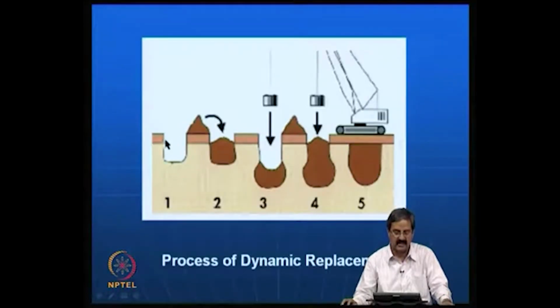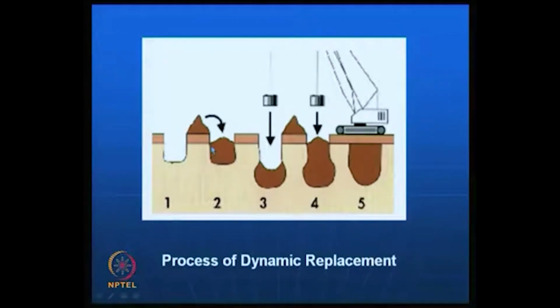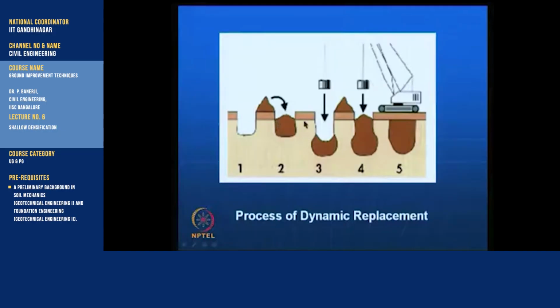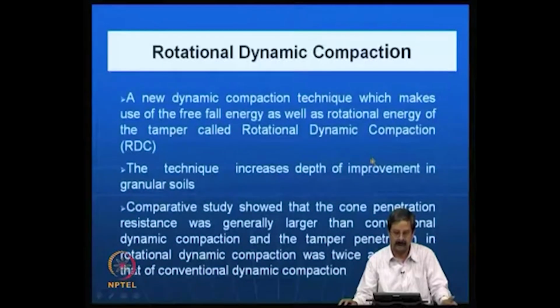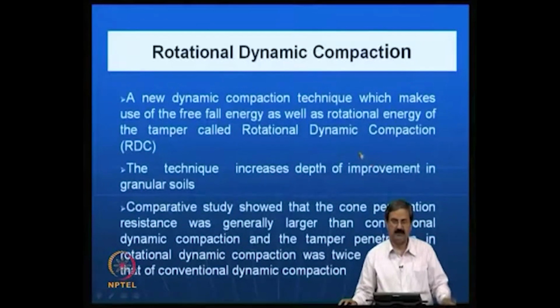So you just excavate, and it is actually what we call dynamic replacement. There is a lot of terminology, but the principle is very simple: you have clay, then you have this material, you compact it again and push it in. So you are trying to replace the weak material in this manner, introducing a good material in the place of the weaker one. That is what we call replacement, so that is also possible.